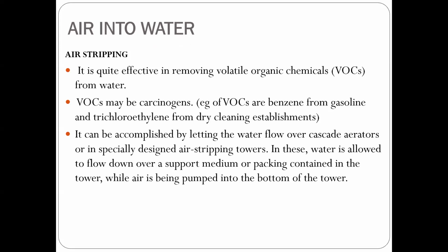These VOCs are benzene from gasoline and trichloroethylene, which may be present in a dry cleaning establishment. So they may enter into the water whenever we are carrying out our raw uses of water. So we have to remove those. That is nothing but air stripping.